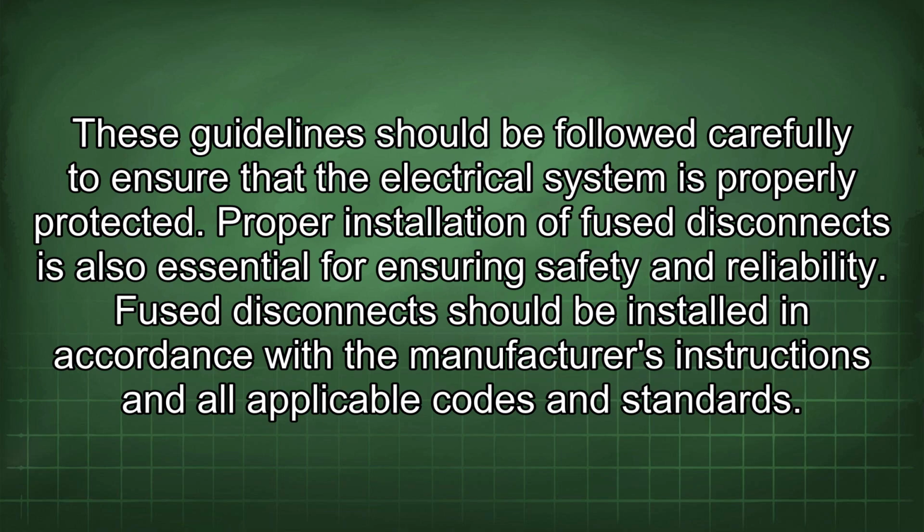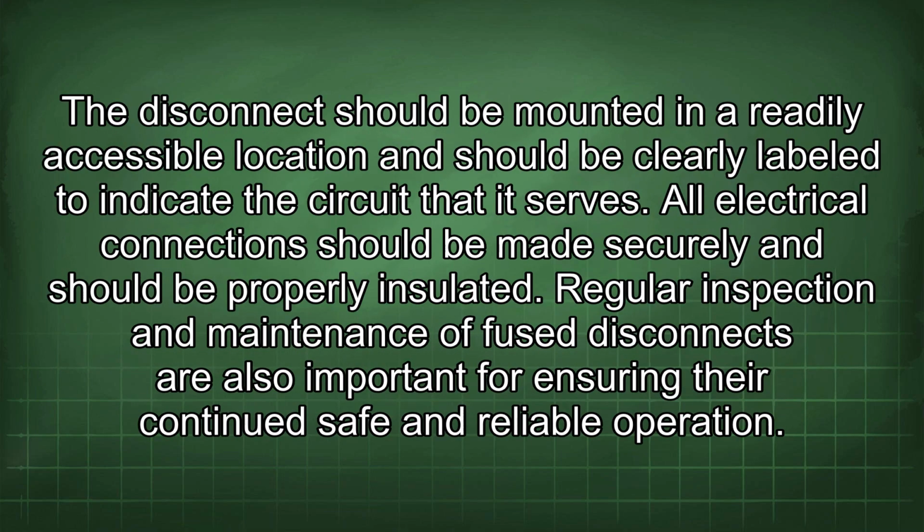Proper installation of fuse disconnects is also essential for ensuring safety and reliability. Fuse disconnects should be installed in accordance with the manufacturer's instructions and all applicable codes and standards. The disconnect should be mounted in a readily accessible location and should be clearly labeled to indicate the circuit that it serves. All electrical connections should be made securely and should be properly insulated.